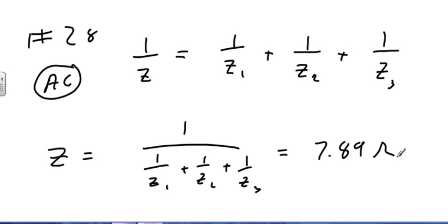It was treating the impedance the same way as we treat resistance. But the impedance, if I have some X of L, it's that way. If I have some X of C, it's that way. So my impedance is some number that's a magnitude and an angle. So impedance 1 is some magnitude and angle. Impedance 2 is some magnitude and angle. Impedance 3 is some magnitude and angle. If my angle is 0, don't call it impedance because now it's resistance. Okay?